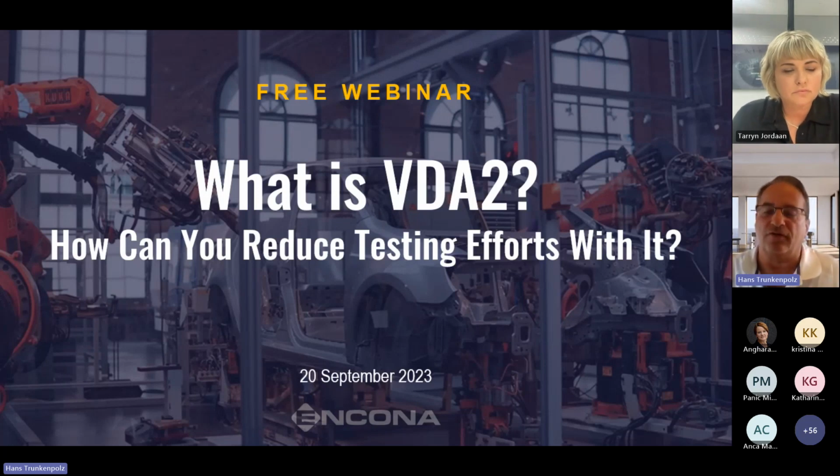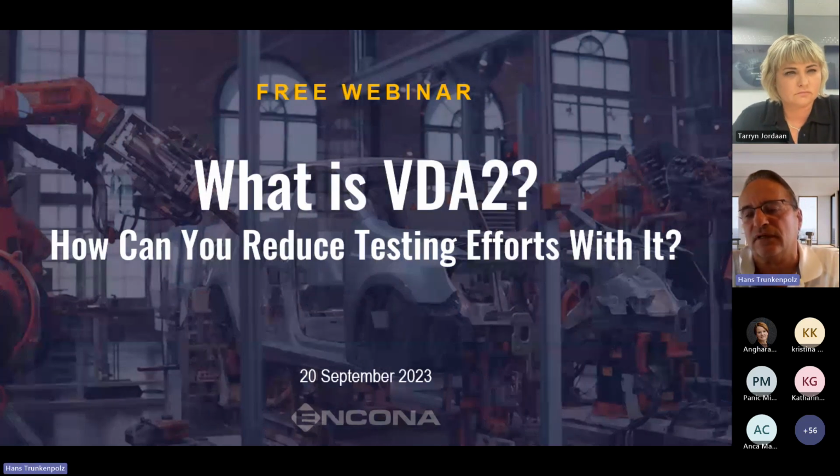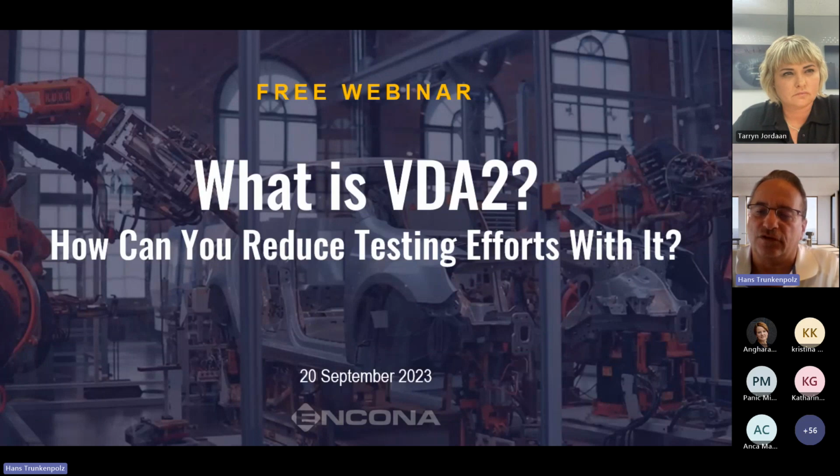now the supplier to come forward with a proposal as to what we're gonna measure, what we're gonna test, what we're gonna submit during the course of a PPAP approval or a PPA approval in VDA 2. And that is a complete turnaround. That's a complete change of paradigm. So the expert of the technology, the supplier, is now coming forward with a proposal by applying the product and the manufacturing process development risks, and coming up with a proposal in various different areas to suggest to the OEM or to the customer above, wherever you find yourself in the supply chain: this is my proposal, how we deal with that.